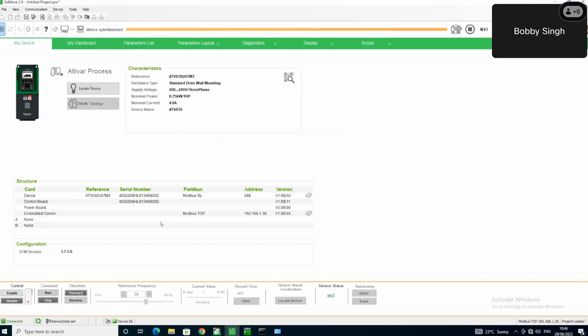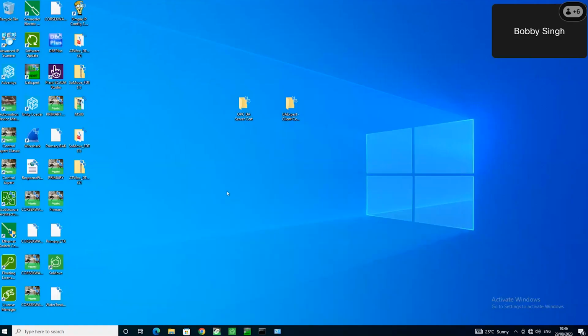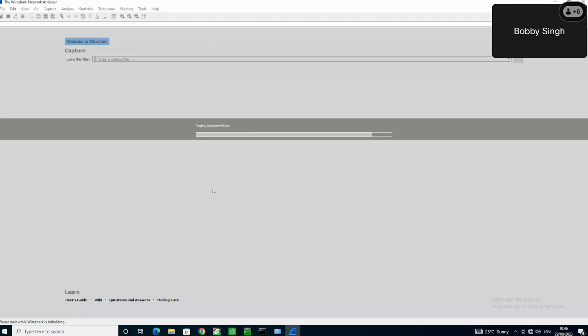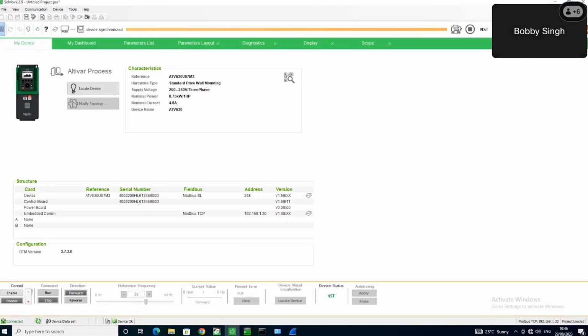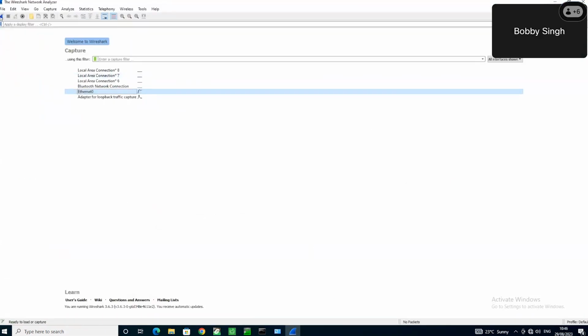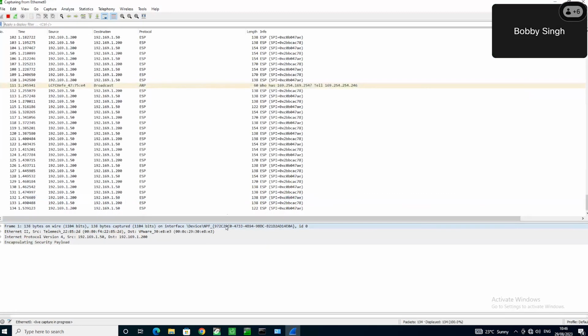As you can see, before, IP security was disabled, then I set up the IP security and created that tunnel between the engineering workstation and NUA, and I was still able to successfully access my VFD that's on a private M580 distributed I/O network, an isolated network. Let's take a peek at Wireshark and what that looks like now. Earlier we saw it traced all the Modbus TCP messages, so we're going to try to do the same while my device is connected. So let's see if it still shows us Modbus TCP messages or anything else.